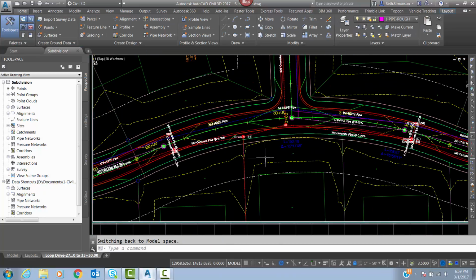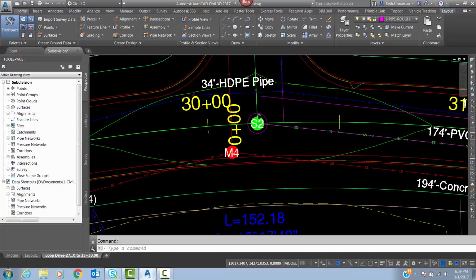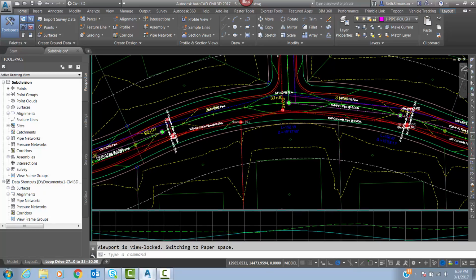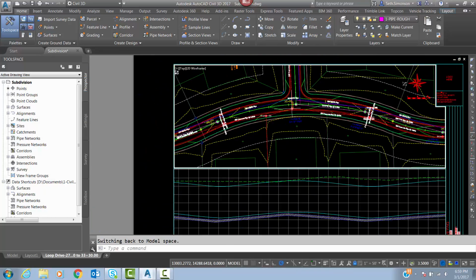So one thing I'm going to do is I'm actually just going to go in here. Yours should come in because you should have already graded out all your pipes. For some reason it didn't stick in this drawing. One thing just to kind of cover again is I can set all these structures to go, since the storm all goes along my road surface, or my sanitary goes along my road surface, I can set all the rim elevations to the road finish ground all at once.